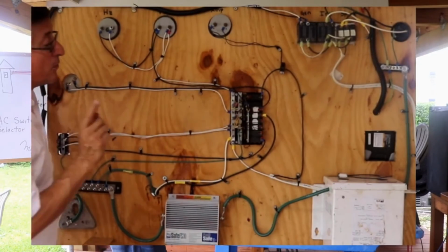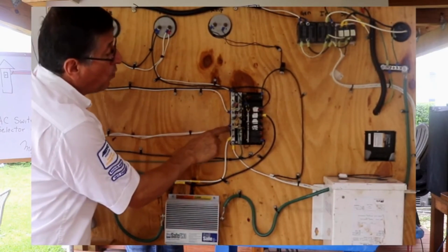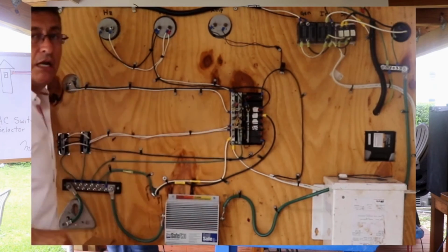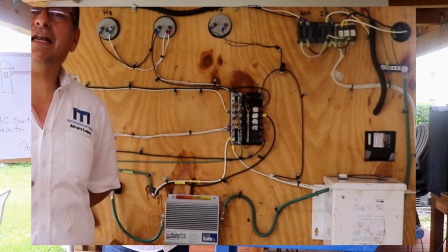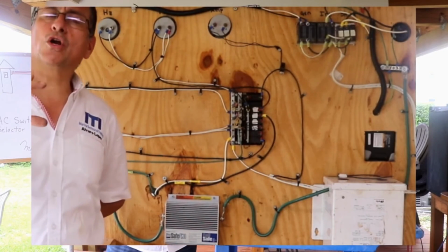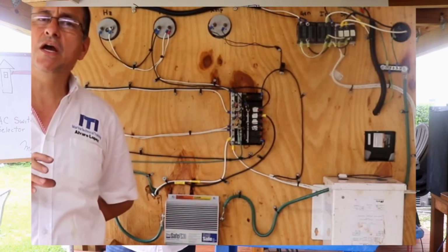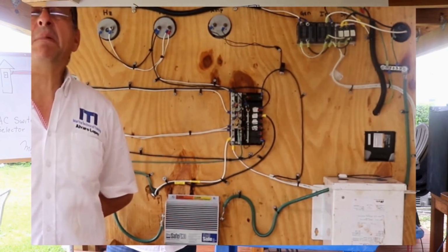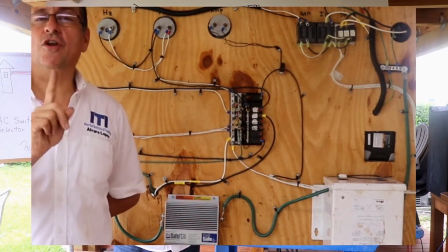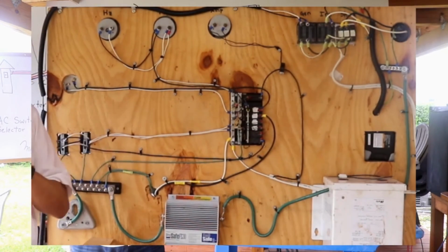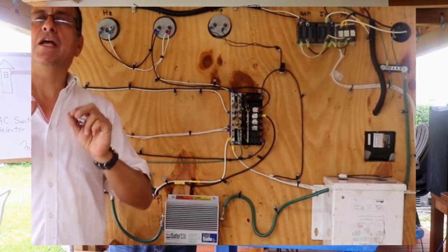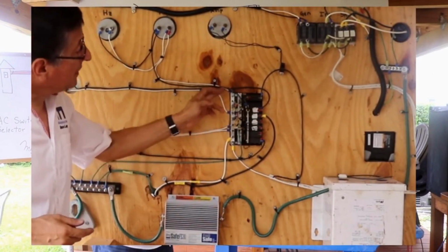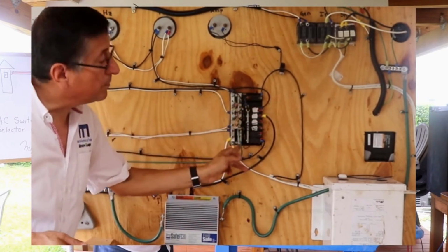What happens if for some reason you put one equipment and connect the neutral with the ground, or the ground with the neutral? There are technicians, electricians dedicated to residential or industrial electricity, and they say that the neutral and ground can be connected together. This is not possible in marine applications. Remember, in marine applications, only at the source of the power, neutral should be connected with ground. After that, they should be separated: separated bus bar for neutral and separated bus bar for hot.